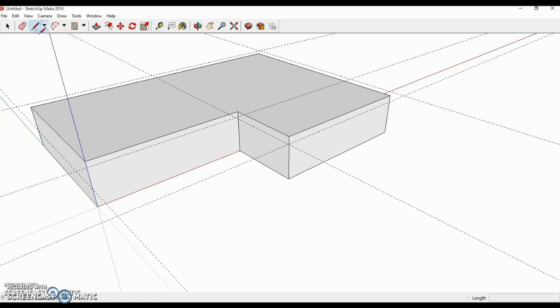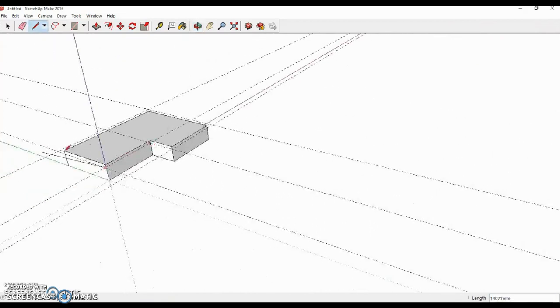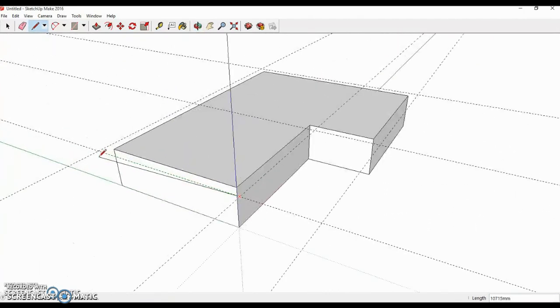So now having that complete, you can use the pen tool, and you can go from these intersection points, and draw a line connecting to this intersection point. You then find the midpoint of this line, which will be a blue circle, and you want to come up from the midpoint 3,000, and it'll be on the blue axis. You then want to go down to the end and connect it up, and then again from the top and down to the end, and you'll have a triangle.